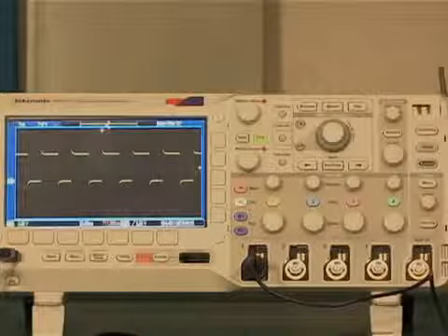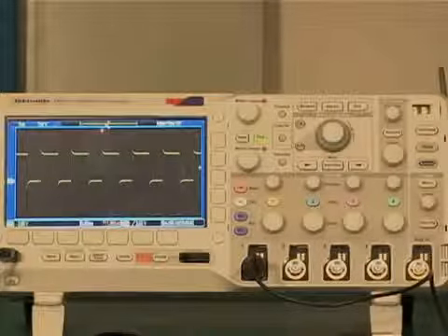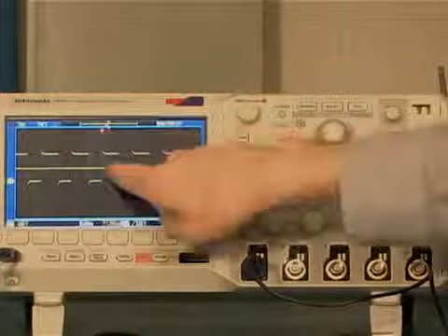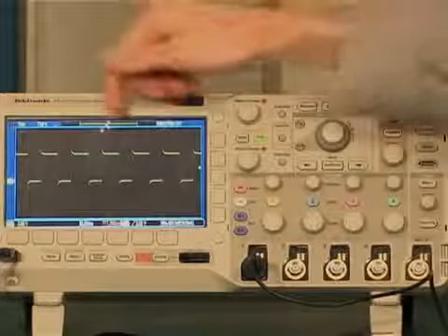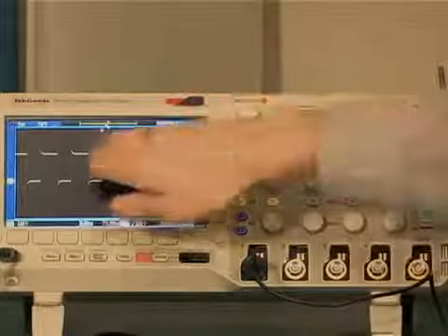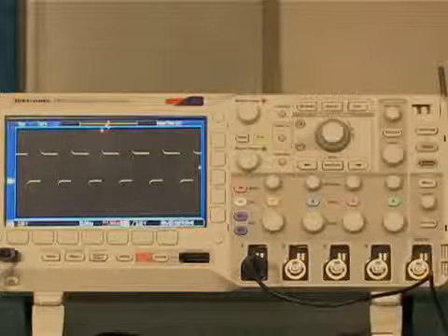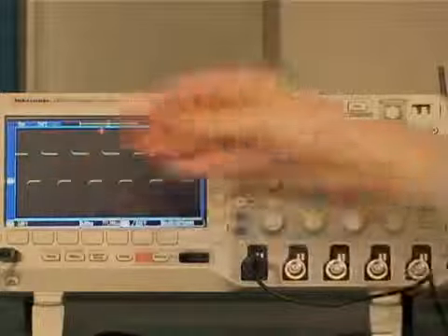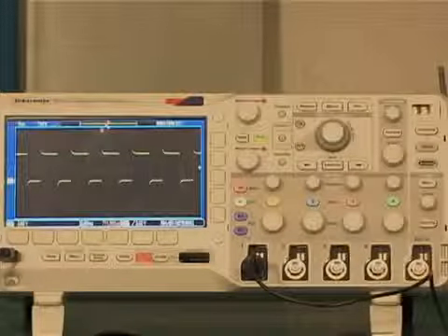So whenever it's time for the scope to update, it waits until the voltage crosses through this level, and then it marks that point with the trigger indicator. It says this is the start of the signal, and it updates. And notice it's also able to display a little extra data before the start of the signal. How it does that is a discussion for another day.